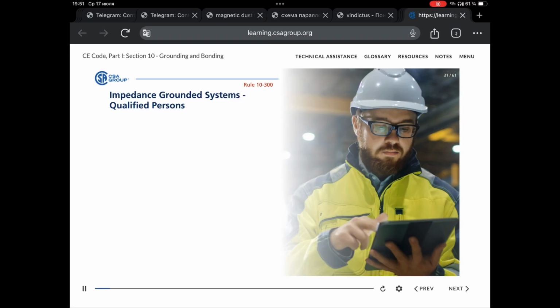The most common type of low-voltage system that can give advantages without the disadvantages is called the impedance-grounded system. Often these systems are referred to as high-impedance or resistance-grounded systems because of the addition of a neutral grounding device, usually resistors, in the grounding conductor of the transformer.